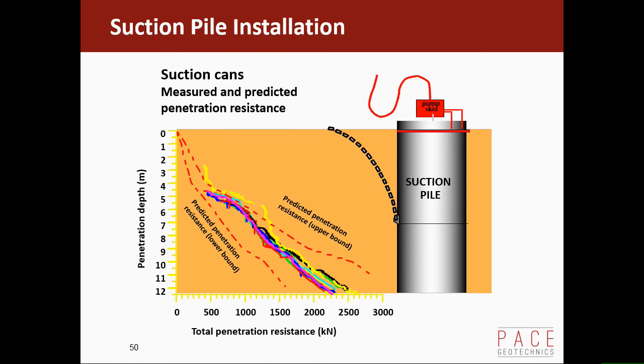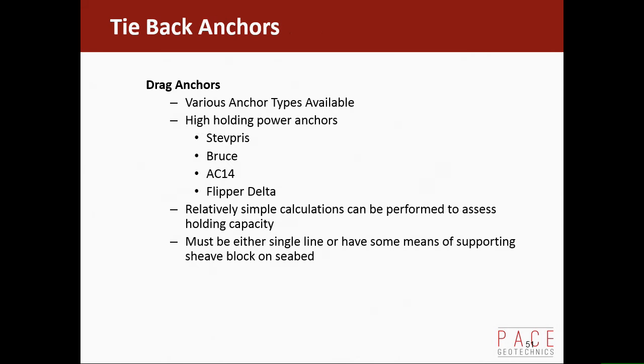If that leaks a little bit over 25 years, that small leak actually becomes a significant amount of water. If it's only, say, a 10-year storm going by for 3 hours, not much water is going to go through that small leak, and you can be reasonably confident about that. Because with a 25-year design life and 10-year return period storm, you might have 3 during the life of the pile, so it's not going to be a significant volume of water. So, okay, suction piles are only suction for installation.